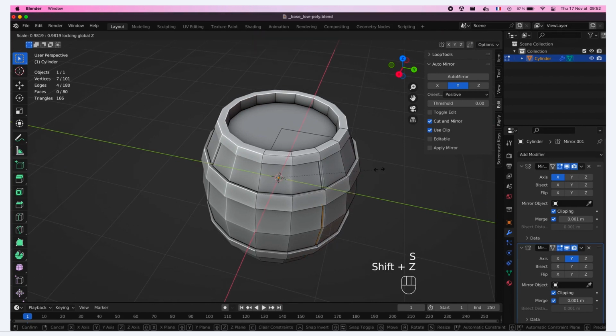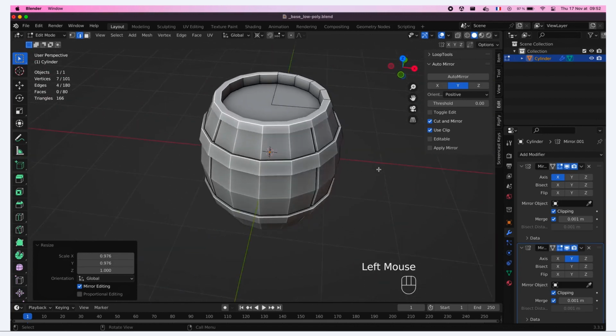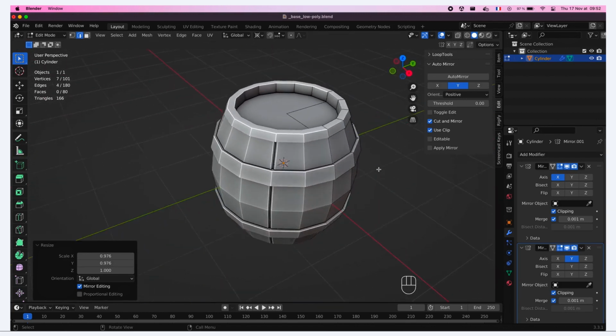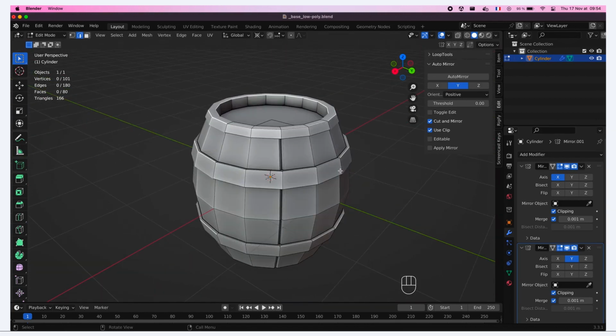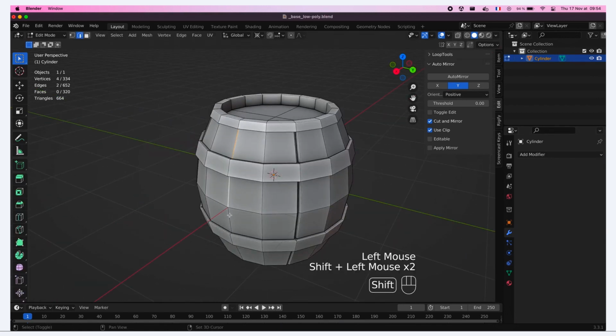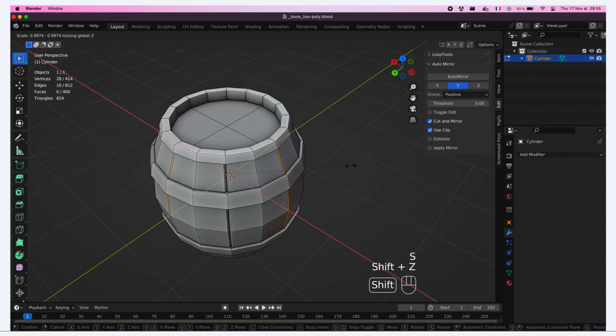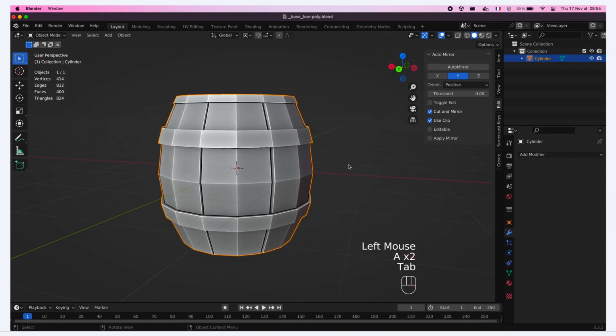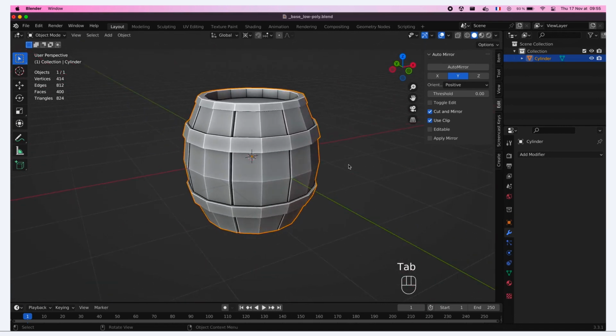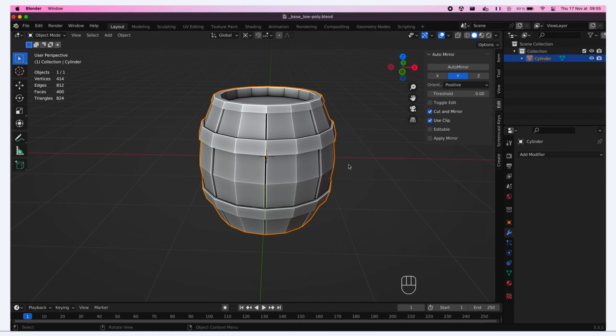And now if we scale along the X and Y axis, we see that we have a nice delimitation between our 2 planks. For the other dents, since they are on the mirror planes, we first have to apply our mirror modifiers and then reapply the same bevel then scale technique at regular intervals. In the end, we get a really cool visual with curved wooden planks and the metal bands circling them.